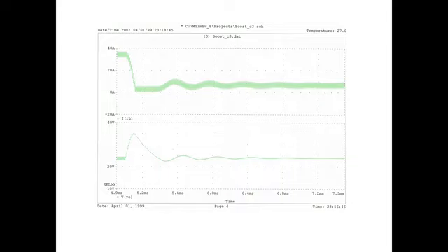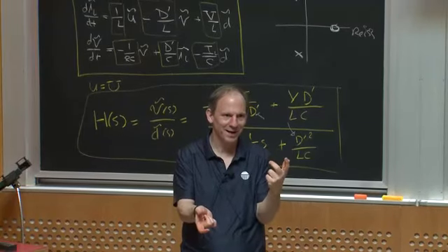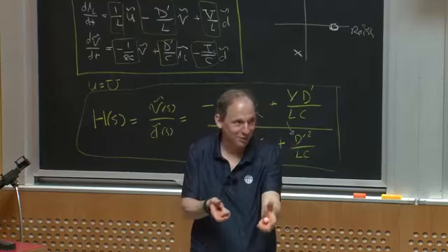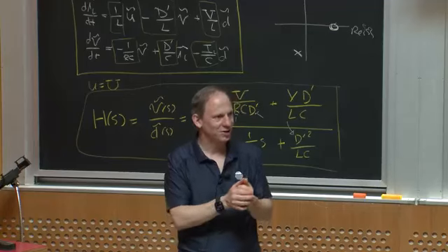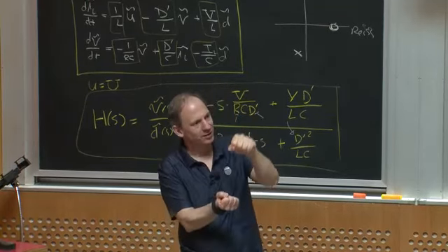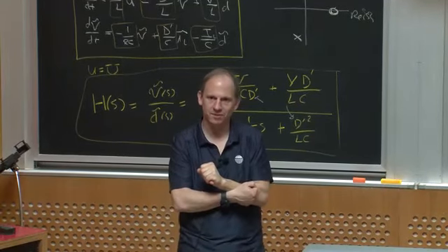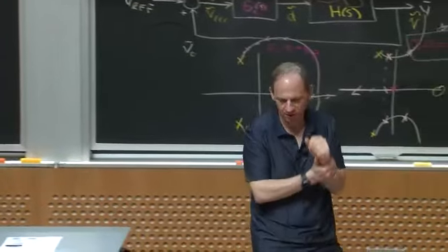okay? So when you're thinking in your design projects about how to size L and C and you want some cutoff, using a 1 Henry inductor and a picofarad load filter capacitor is probably a bad idea because you got to eat the energy in that inductor in the load transient, right? So word to the wise, you got to size those very wisely and make sure you have enough energy storage in your capacitor that it's not going to be too unhappy to absorb the energy from the inductor in a transient. Okay?